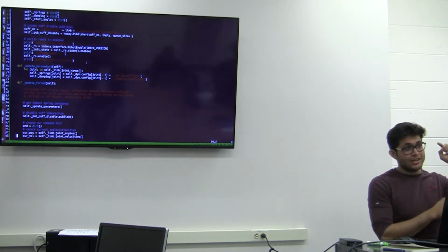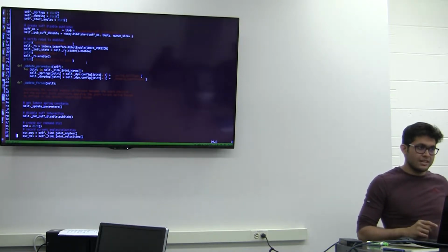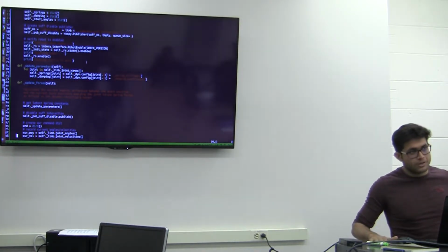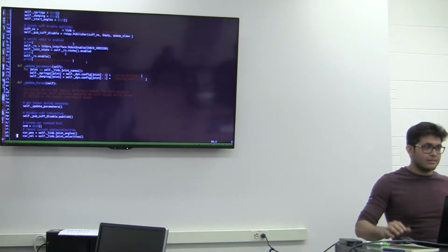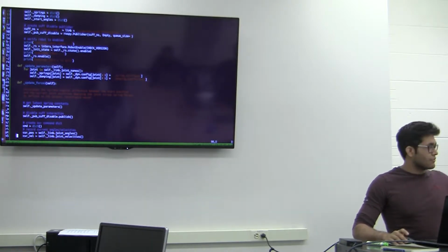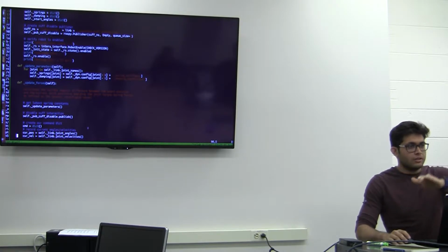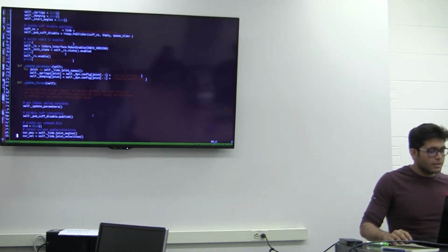When it moves to the start angles, it doesn't read through the URDF, it just moves the joints directly there. So if the URDF doesn't know about the platform you're seeing right now, you just go and hit it, right? So make sure never to change the start angles unless it's extremely important. Start from the home position, and add an extra command to go to that position if you want to go there. Don't change the start angle.